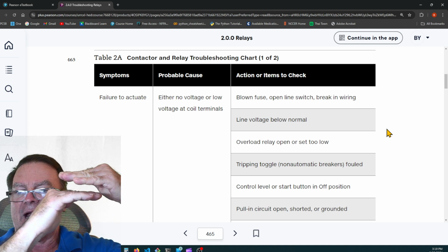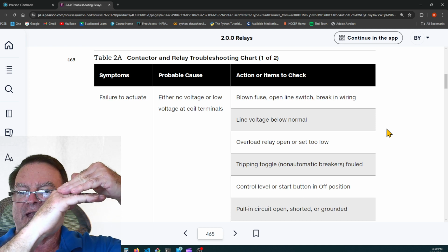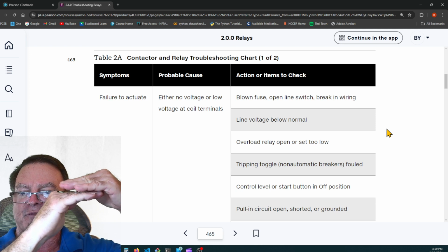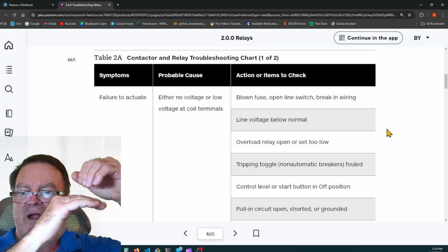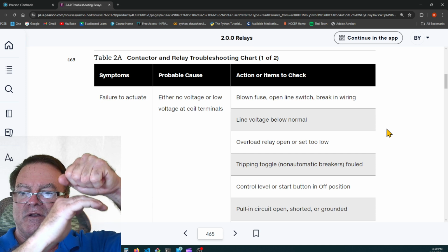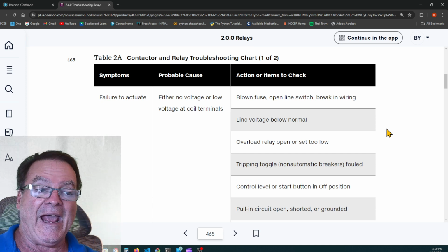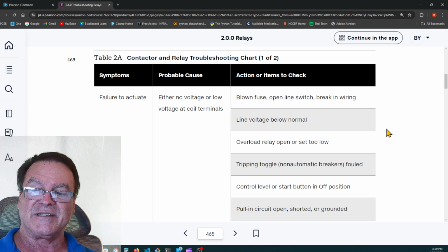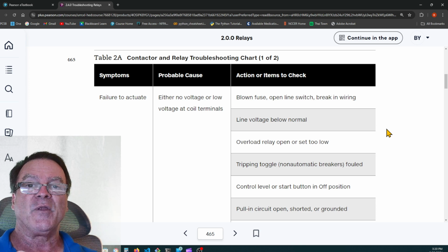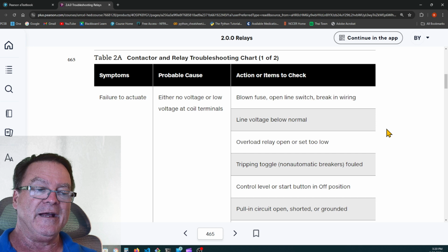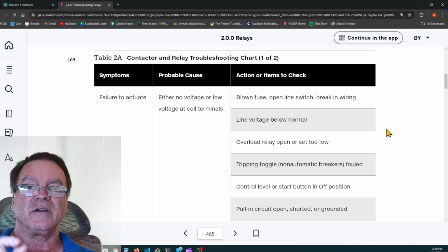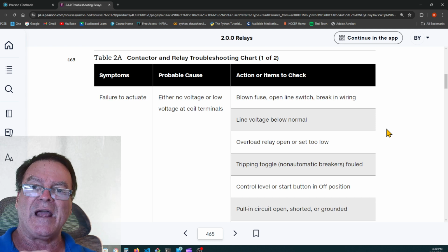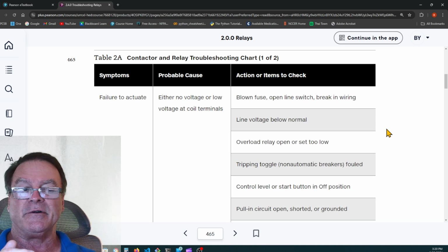If they were flat, you could get a little bit of a gap in there. You could get a little bit of debris, and it would keep them from making contact. But the rounder ones always make good contact. And there's a tiny little arc when they make or break, and that tiny little arc melts the surface of the contact, and then it solidifies back to that nice round feature.